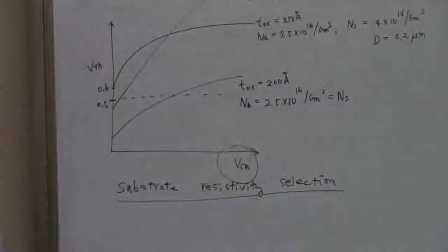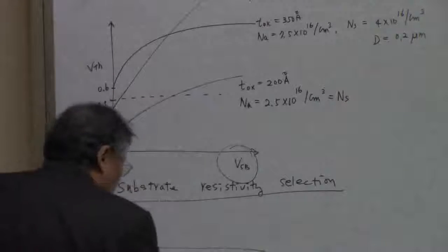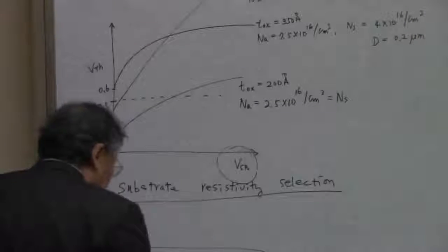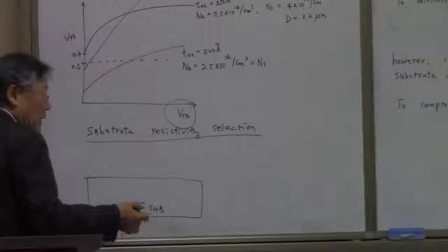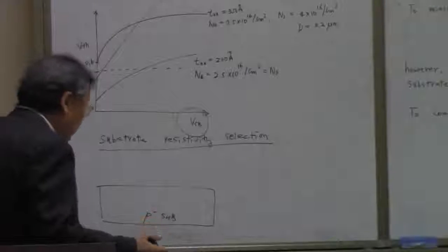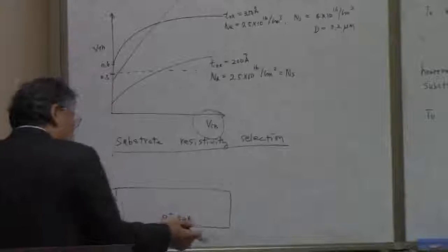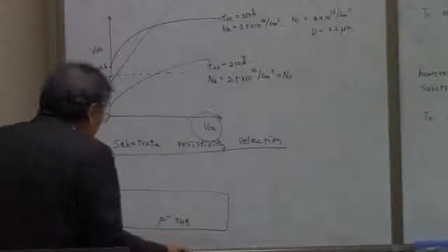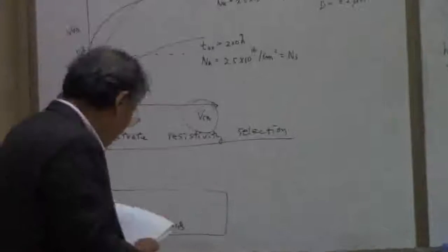What kind of materials to begin with? If you want to set up the MOS, for example, you start out with the P-type substrate, and then this P-type substrate, the doping has to be done on the Czochralski growing to wafer preparation. It has been done during the wafer preparation, right? And this, what the doping level should be to have a reasonable device to be built on that wafer.